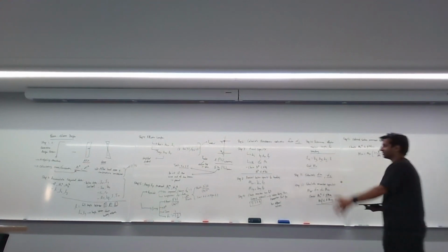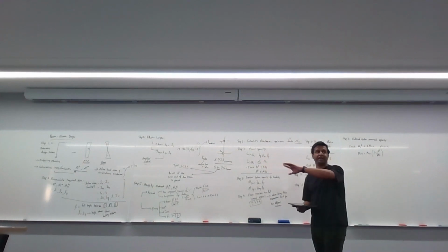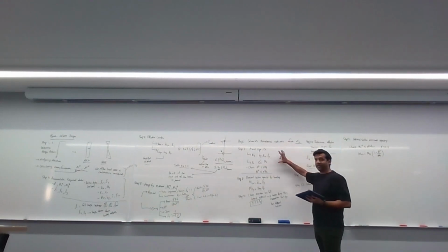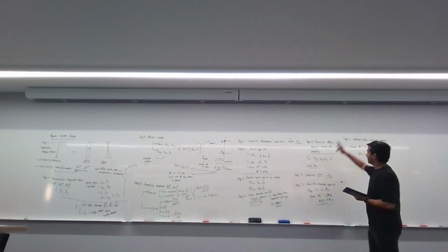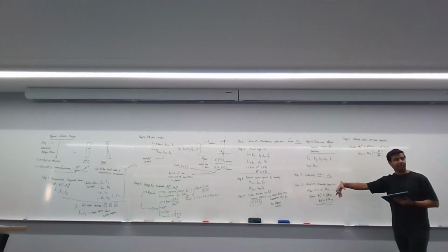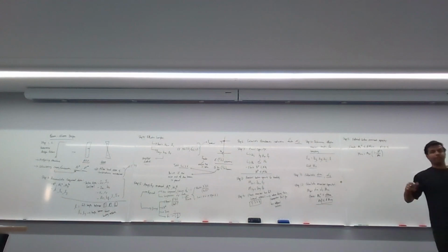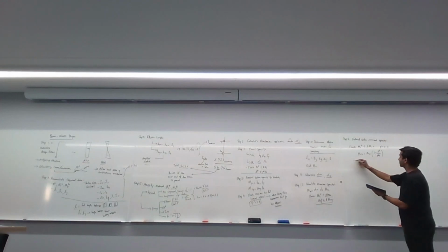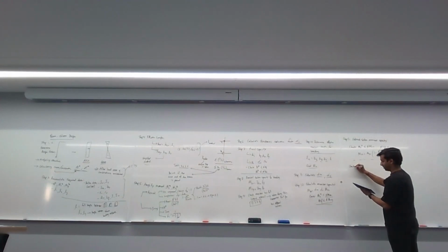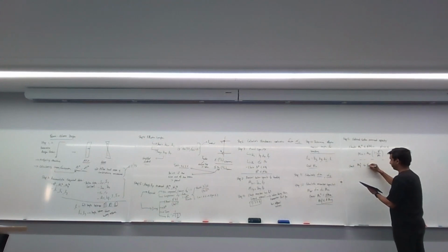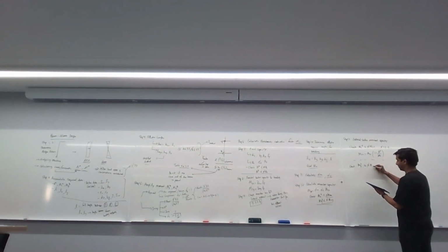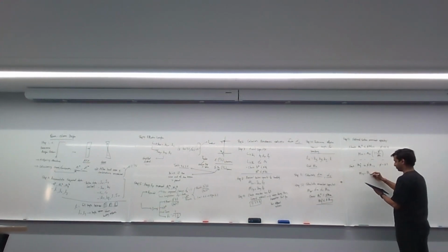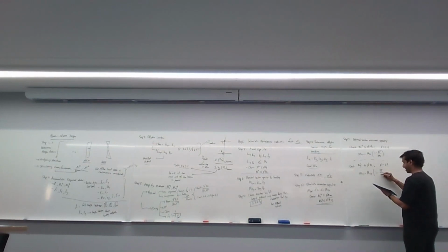Remember, if you have a look at the steps that we've done so far, steps 1, 2, 3 are really your analysis stage. 4, 5, 6, 7 are the axial check. 8, 9, 10, 11, 12 are the bending check. From this point onwards, we're doing the combined check. So checking the fact that both of these are happening together. So you check against the reduced Mrx, and you also have to check My star less than or equal to phi Mry. And remember, phi is equal to 0.9 here, where Mry is equal to Msy, 1 minus N star over phi Ns.